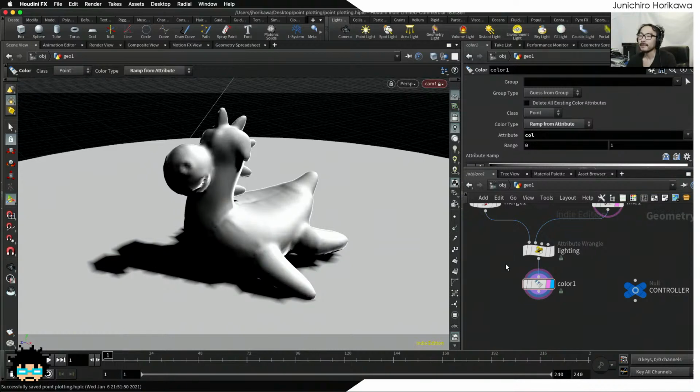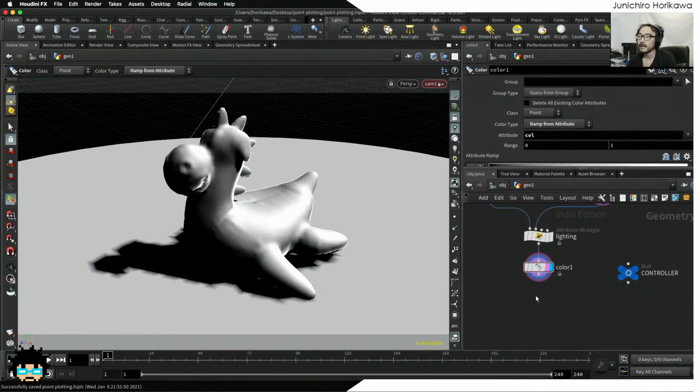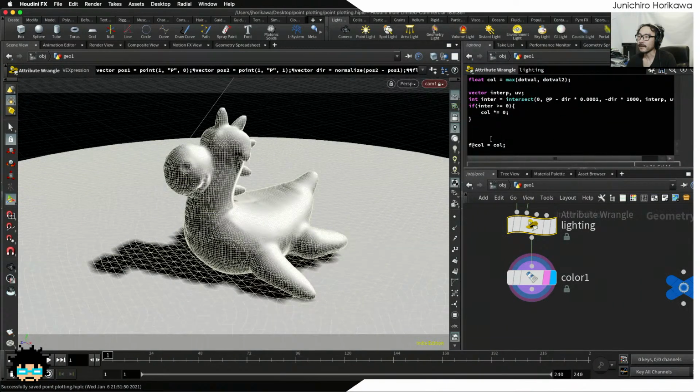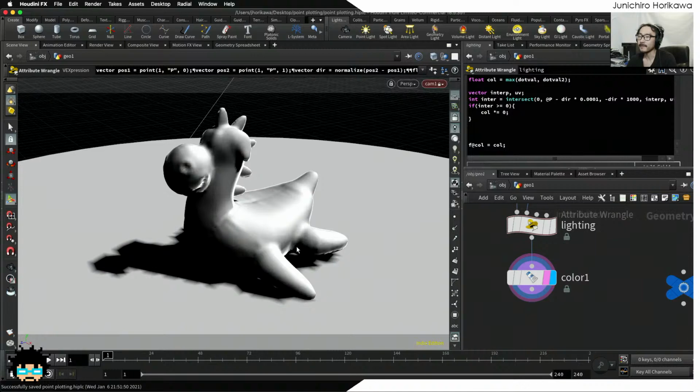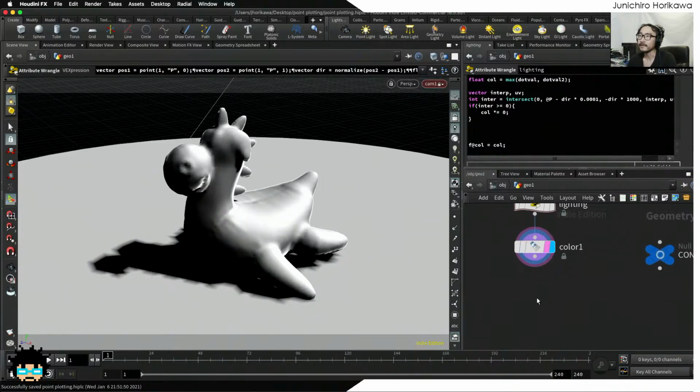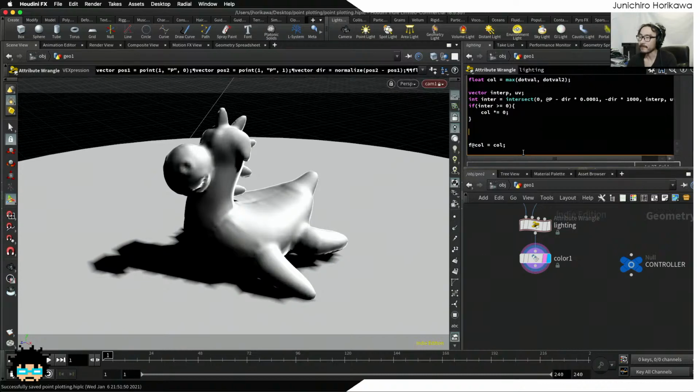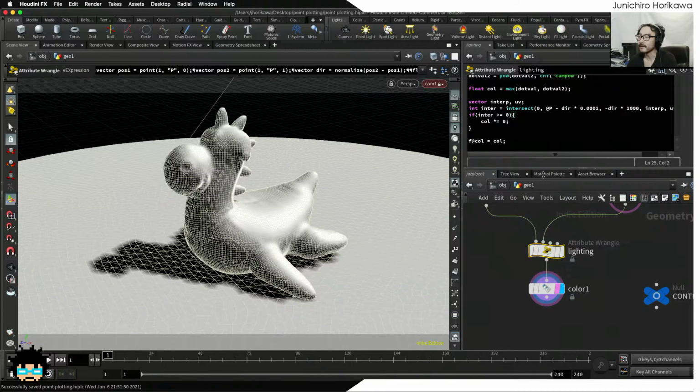Okay, so to remesh based on the color value here, the shaded value here, I need to set some attributes derived from this color value, which is in between 0 to 1. And each of the floor and the object has a different range for the mesh target size. So I am going to set the size for each of the geometry with those range informations, and I'm just going to do it inside this wrangle right here.